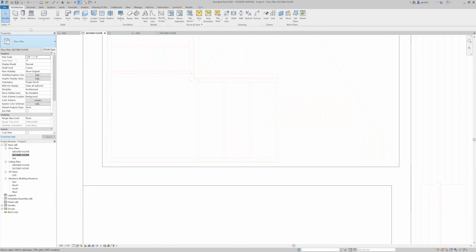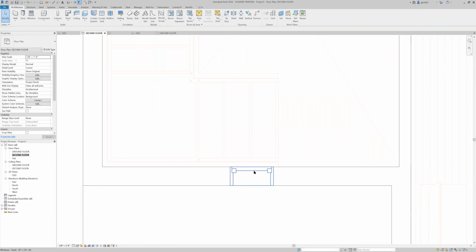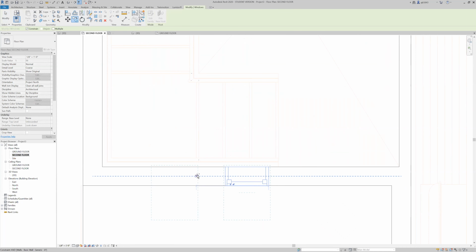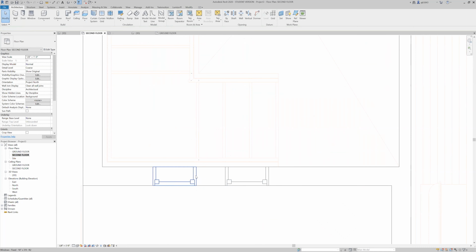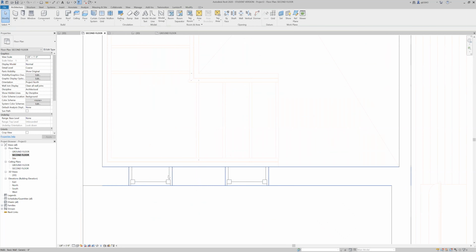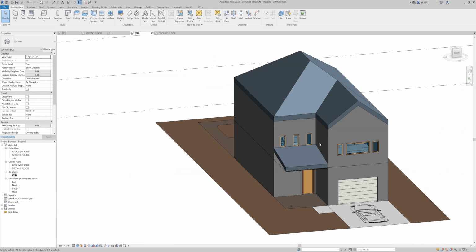And this wall, we have 3 more of those 18-inch windows. Since I already have them made, gonna place one in the center. So we're at 5'6" and 5'2". So gonna want that to be at 5'4". Then I'm gonna take this one, move it 2'6". Again, this can be somewhat arbitrary. Maybe I want it to line up with my staircase there. So I'll move it a little more to the left. Let's do a 3'4" works, and then I can go ahead and mirror that across my center window, giving me 3 nice windows there.